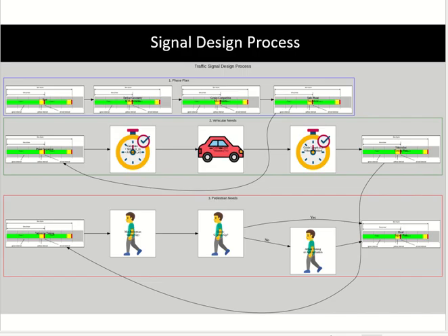So you calculate the loss times for each lane, it can be different. And then you find out the yellow time and all red time. Yellow and all red have fixed equations. You can find out yellow and all red depending upon loss times and intersection space, intersection size.